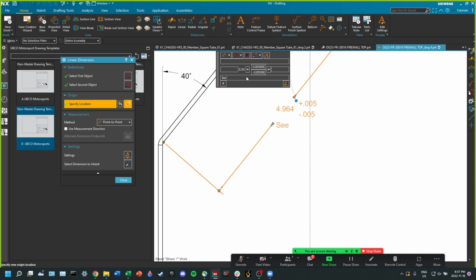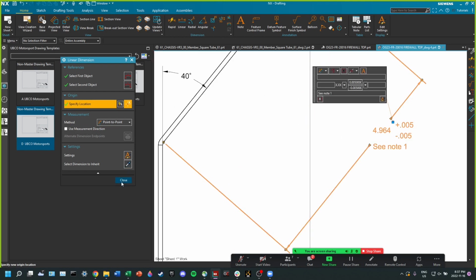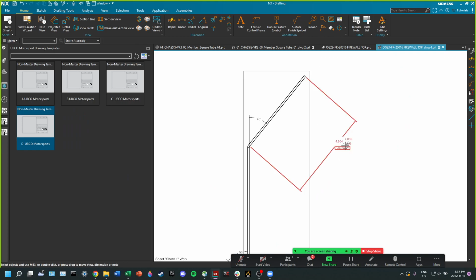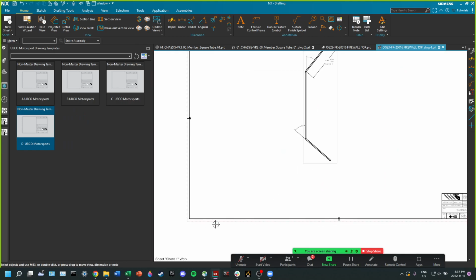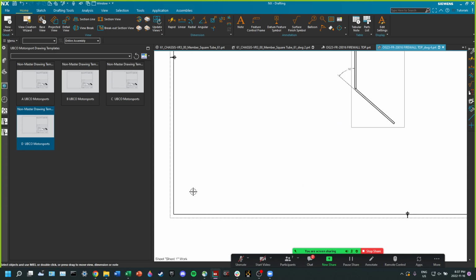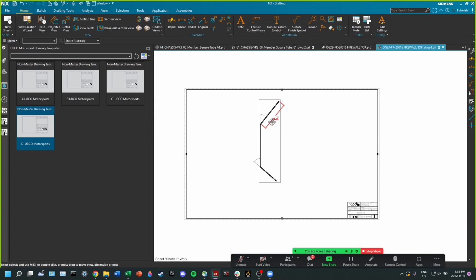C note 1. And that'll tell whoever's looking at this drawing to go look at the note section of the drawing, and they'll go down in the notes and see that note 1 says the surface is a bearing surface, keep tolerance; the tolerance should be on the dimension, but follow tolerance, sort of thing.